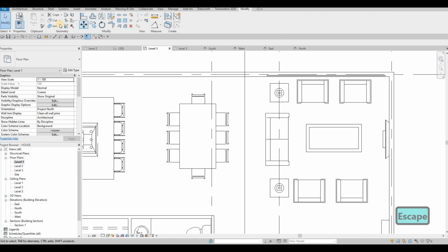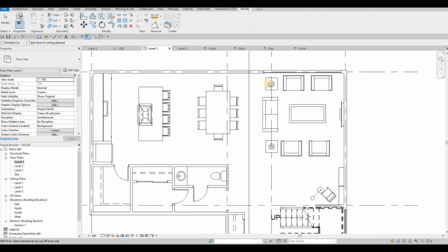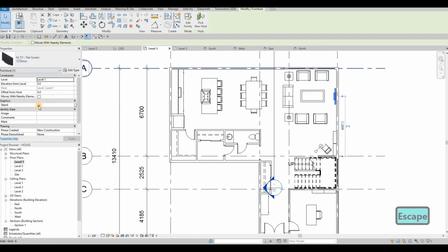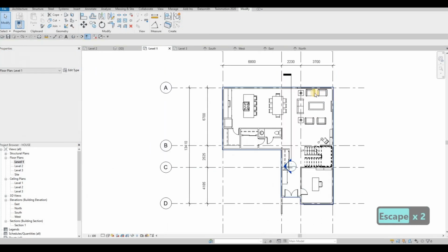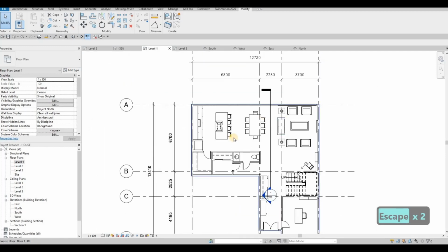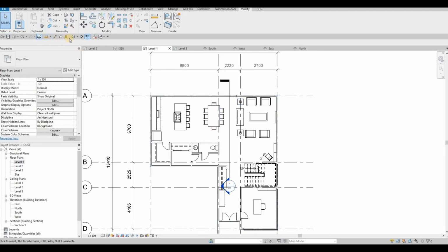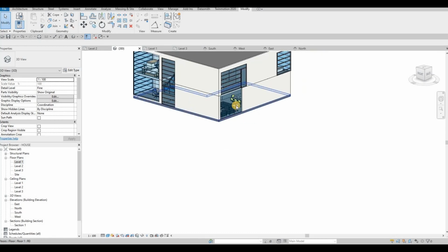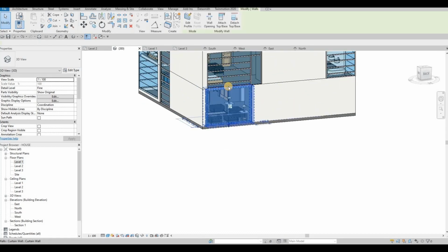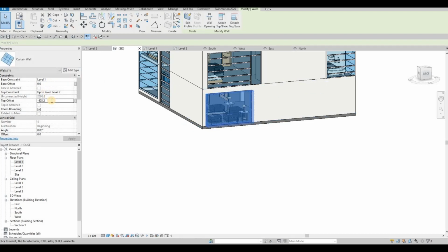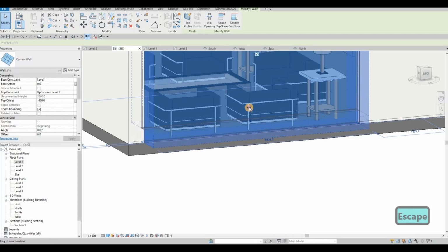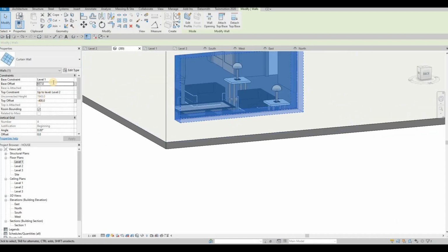So we're going to do the same design that we have. So we have it there. Let's remove the stand so that it is wall mounted. I think that's about it here. Let's go to 3D and then just pull this one down. Maybe it's -400 from the top, and then here from the bottom, let's just pull it up. Base offset probably 700.